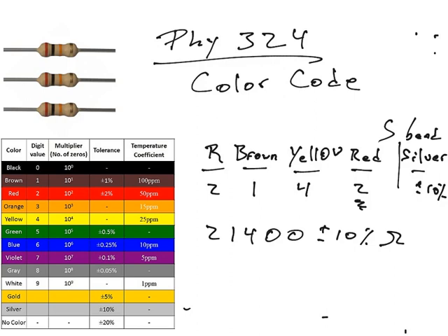5-band resistors, because you can be more precise with the value, they're machined more precisely, then you may want to know more digits of the number. It doesn't mean that the actual resistance is bigger or smaller or anything like that. In fact, you could have a 5-band resistor that's 20,000 ohms or a 4-band resistor that's 20,000 ohms. It's just that the 5-band resistor likely will have a tolerance that's maybe plus or minus 1%, whereas a 4-band resistor is probably plus or minus 5 or 10%, because you don't need to be so precise. But that's all there is to it.